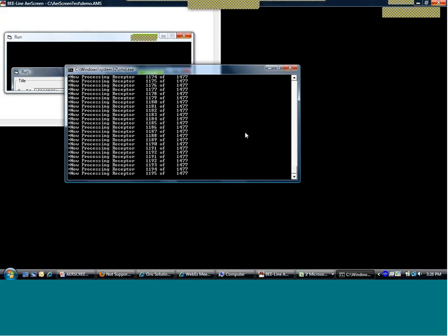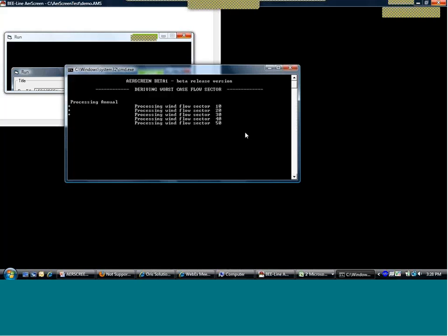One thing that I ought to point out is that one of the things that AerScreen does that Screen 3 did not is that Screen 3 always assumed you had a single plume centerline. And that's a little different than what we have here, in that Screen 3 is looking at moving the plume relative to the source-receptor geometry, which is, again, part of why we have so many receptors.